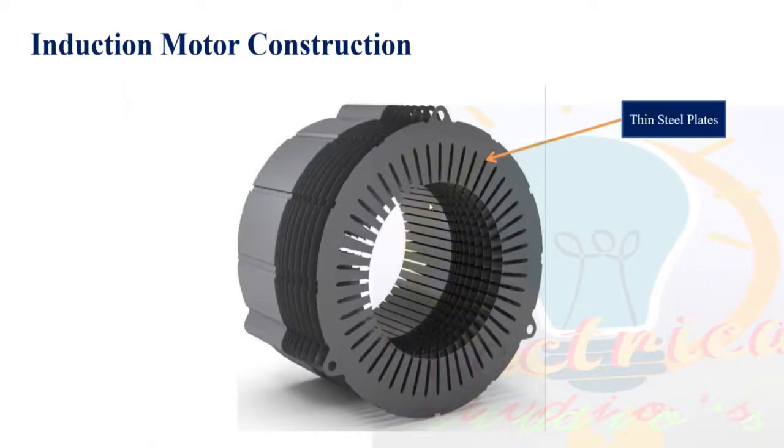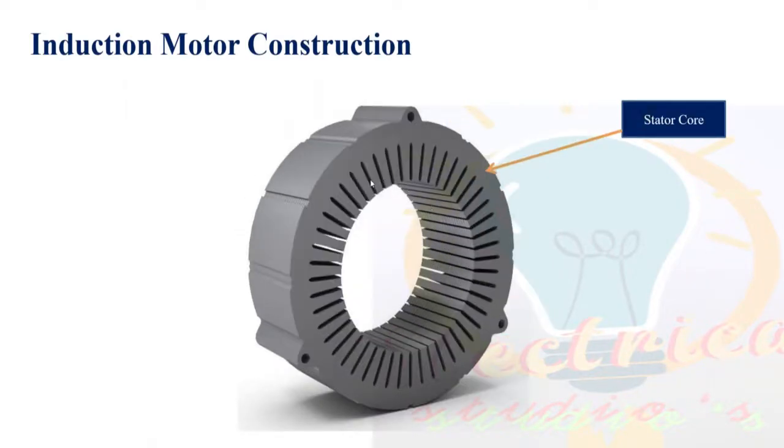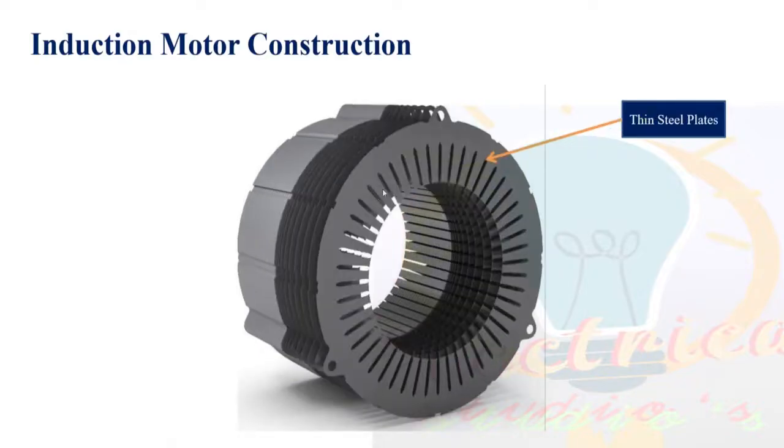And the stator cores are what? Stator cores are nothing but thin laminated steel. So very thin laminated steel. When you take the electric vehicle stator application, either it's the PMSM or any type of motor, the very important thing is the thickness of this steel.